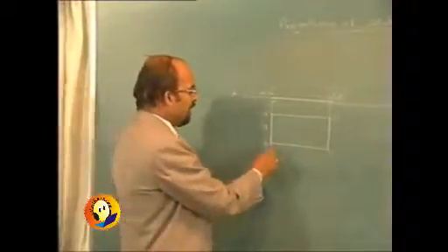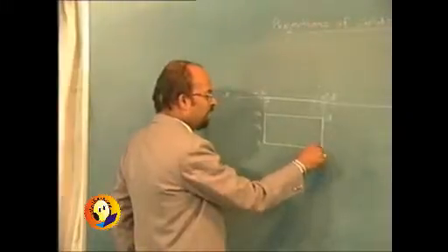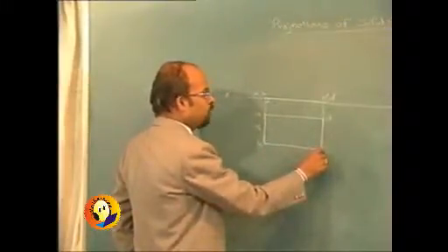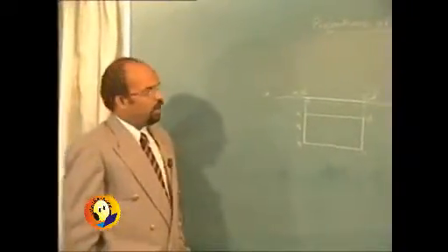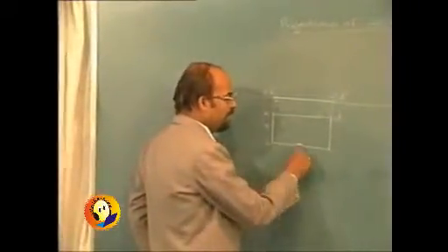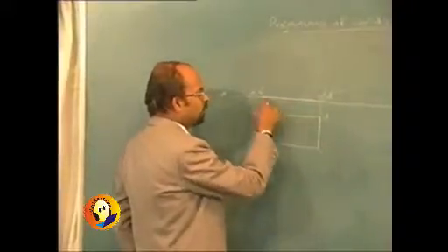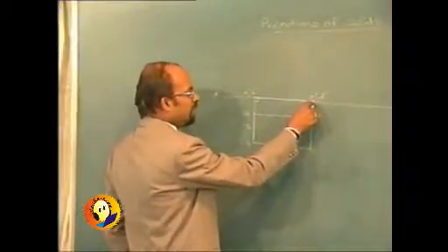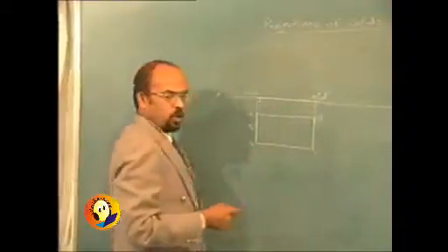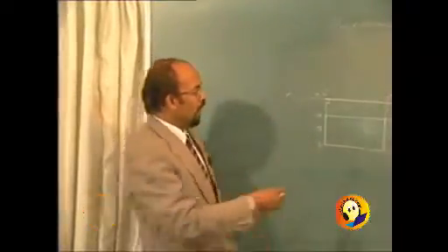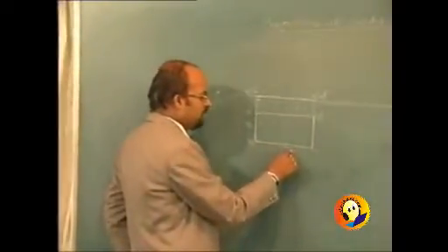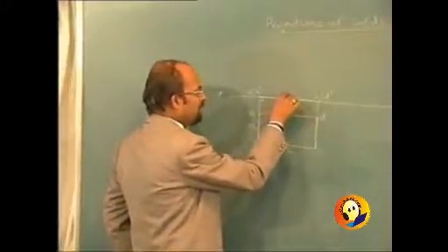If we consider line BC, then that line BC, as its plan is parallel to XY, we can say that the line is parallel to vertical plane. And also it being in HP, it is parallel to HP, so its elevation will be parallel to XY, that is B dash C dash, which is on XY itself, because distance from horizontal plane which will be seen in the elevation is 0, and so BC will be seen in its true length, as well as even in elevation it will be seen as true length.